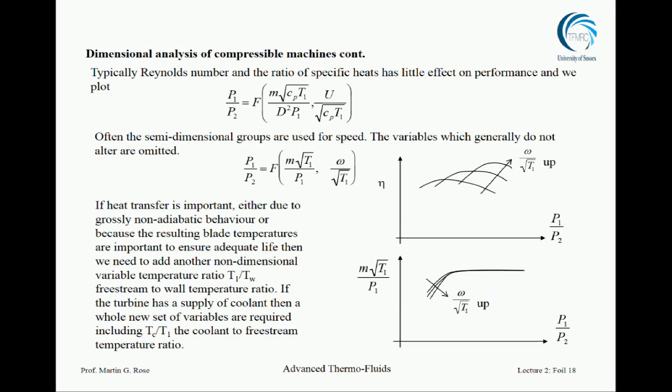If you run a turbine and you plot the capacity and the efficiency against pressure ratio, you get these two sets of curves. The lower one is rather boring. It's the capacity of the turbine against pressure ratio, and it's mostly a constant height straight line. And this is because most turbines spend most of their lives choked. They are passing the maximum mass flow they can all the time. They never unchoke. So that means that you're transonic. The flow is getting up to sonic at the throat and then accelerating supersonically downstream. And the turbine is just flat and straight.